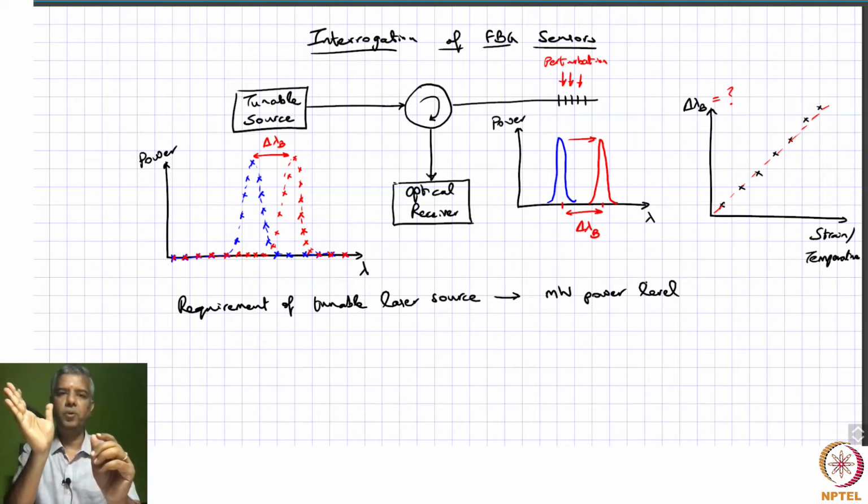Then you put an external grating element, which reflects only one particular wavelength back, and that forms the cavity of the semiconductor laser. When you tune the grating angle, the wavelength that's reflected back into the semiconductor cavity changes. So that is what we call an external cavity semiconductor laser.